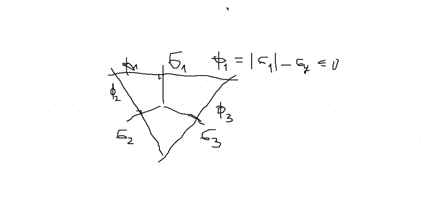Imagine you are here at time Tn, this is your sigma n, and then you jump up there, this is your sigma n plus 1 trial. So you jump out of this one and then you're simply projecting back normally. So your sigma n will be here.